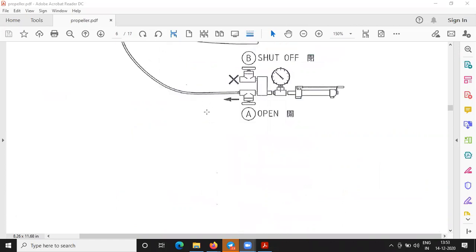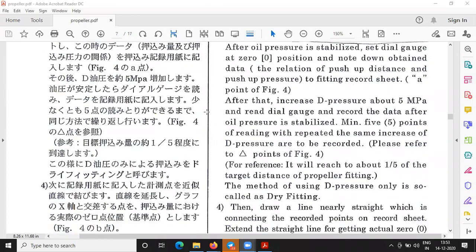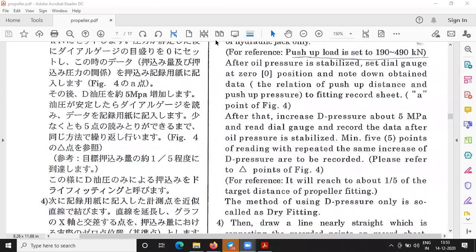Okay, we'll read further. So that means if we are reaching up to the 50 bar pressure, then we'll wait for some time and it will reduce, let's say up to 40 bar it is now. Then further you'll have to see whether the pressure is reducing or the pressure is maintaining. In simple words, we can say this is a holding pressure. It is holding, not allowed to fall back, and it is not moving forward. It is staying there only. That is the simple meaning.